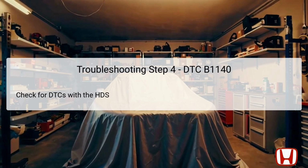The objective of Step 4 is to check for any DTCs again using the Honda Diagnostic System, or HDS. This check will reveal if the system still registers DTC B1140 or if any related codes, such as B1125 or B1126, have emerged. If these latter codes appear, it indicates that additional issues may need to be addressed separately. Finding new DTCs could potentially alter your troubleshooting path, making it essential to keep a close eye on the diagnostic data. If no new codes appear, it could suggest the previous problems have been resolved.